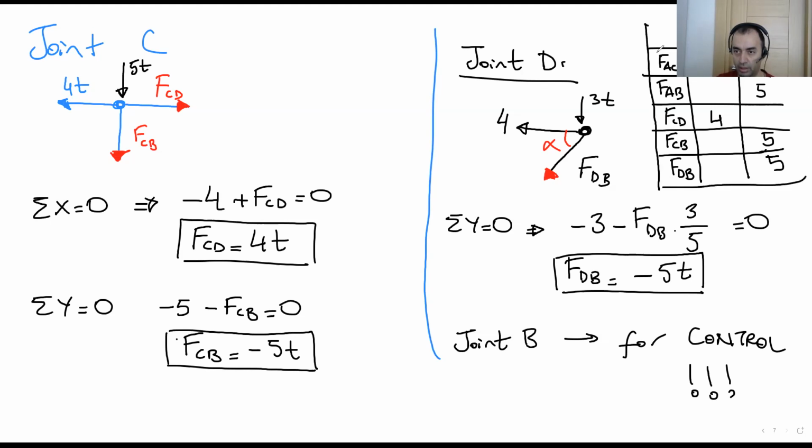After I calculate each load on the members, I draw this table to trace the forces easily. Otherwise, we can't see all the forces on the table. Okay, here is what we did, guys. We are using method of joints. That means if you get a structural system, first calculate the support reactions. It's a rule of thumb before we start our calculation.